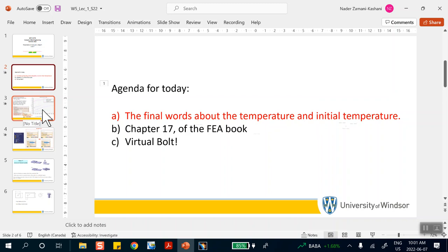Okay, so if that number is there, it's just to remind you of roughly, order of magnitude wise, what the yield strength is. And I already gave you a rule of thumb: knock off 3 zeros from Young's modulus, you're going to be in the reasonable ballpark for metals.